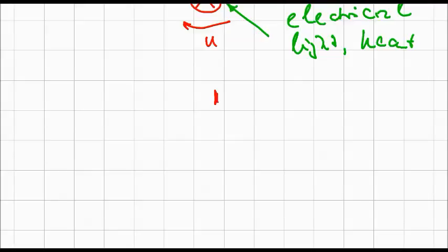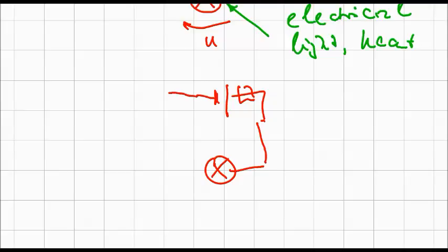So I have my source of electricity, I have my switch, I put my protection up here, and I have my consumer. And instead of running another wire here, I put this to the airframe. So this is the airframe of my aircraft, which is made of aluminum or some other metals, and I put this one here to the airframe, and the circuit is closed in the same manner.